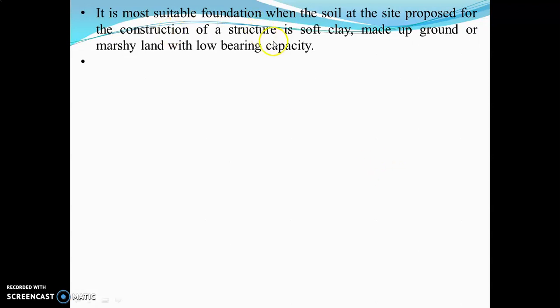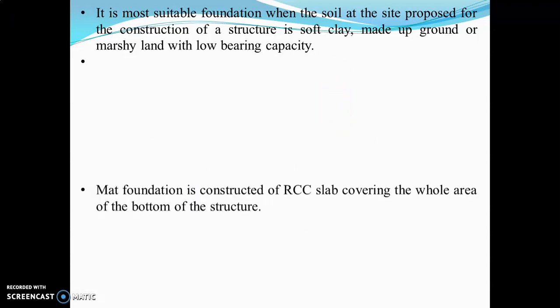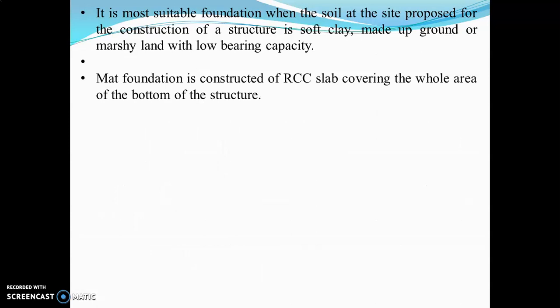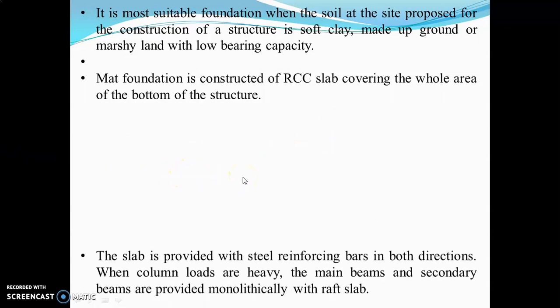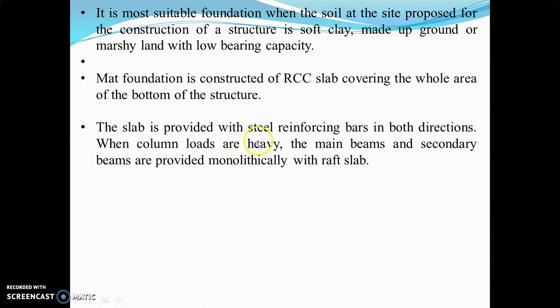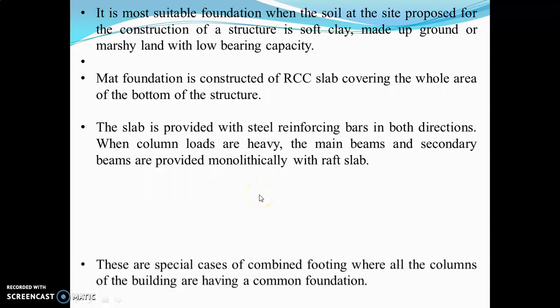Okay, it is more suitable for soft clay soils, and also if the ground is made of marshy land and with low bearing capacity, this foundation is suitable. A mat foundation is constructed of RCC slab covering the whole area of the bottom of the structure. The slab is provided with the steel reinforcing bars in both directions. When the column loads are heavy, the main beams and secondary beams are provided monolithically with a raft slab.